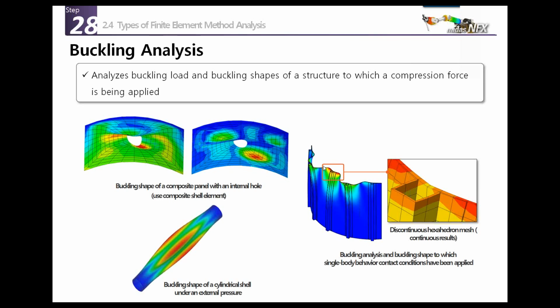But due to the very thin shape of the model, you have some kind of uncertainty, some kind of discontinuity in your analysis, which causes the model to deform. So it is important to understand what the buckling load is, because the buckling load will cause the model to fail much before the yield value. This is why it's important to calculate buckling.